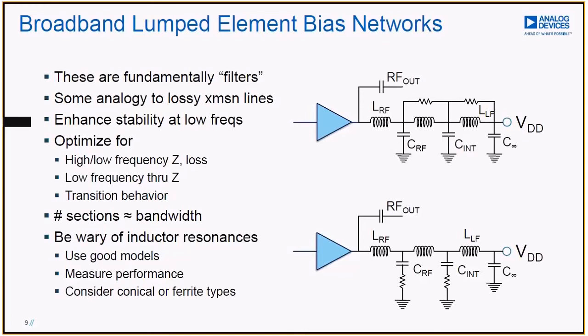So one of the challenges you find is that this network, if you actually sit down and crank the equations for this network, you end up with lots of poles and zeros very quickly, lots of resonant combinations. It looks easy, but it's not as easy as it sounds. So those resistors there are actually very, very important, and we need to design those.